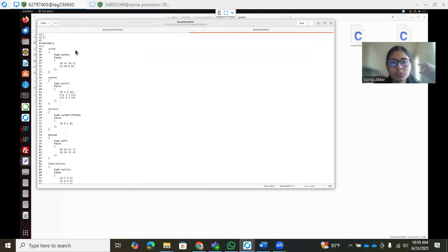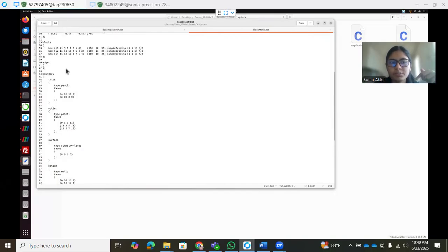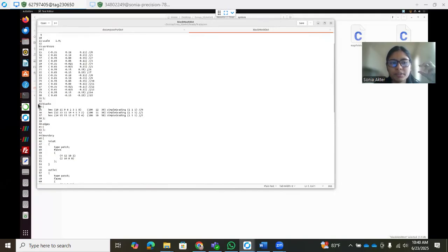But if it's complex, it's better to create that geometry in other software like for example ANSYS, and then compile it here. For our case, because we are running a simple cylindrical case, we have a rectangular domain and we need to put an obstacle. For the rectangular domain, we are using the blockMesh file to create a rectangle, and we are subdividing it into three blocks.